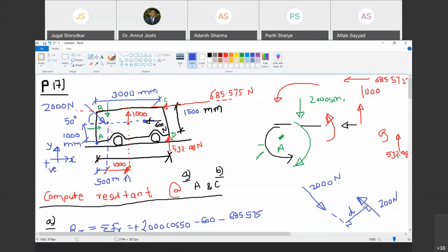Moment of a force changes from point to point, not only in magnitude, it may also change in direction. We discussed this, remember? Yes sir. That is similar to the previous problem where we were taking moment about a point, that was moment of a force. But here, as the resultant is 0, there must be two forces in any direction under consideration which are equal and opposite and separated by a distance, and they must produce couple moment. And as couple moment is produced, the body is subjected to only pure rotation and its magnitude is the same everywhere. Are you with me?